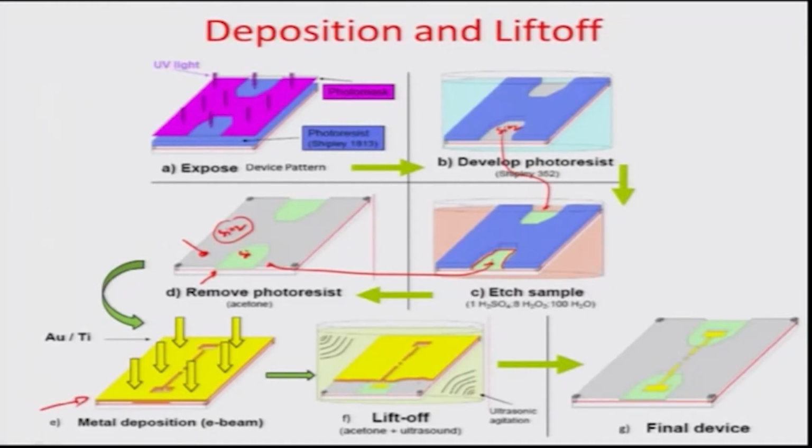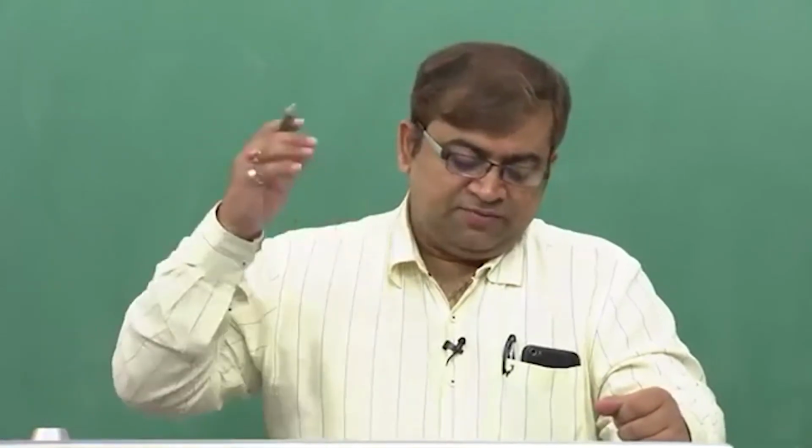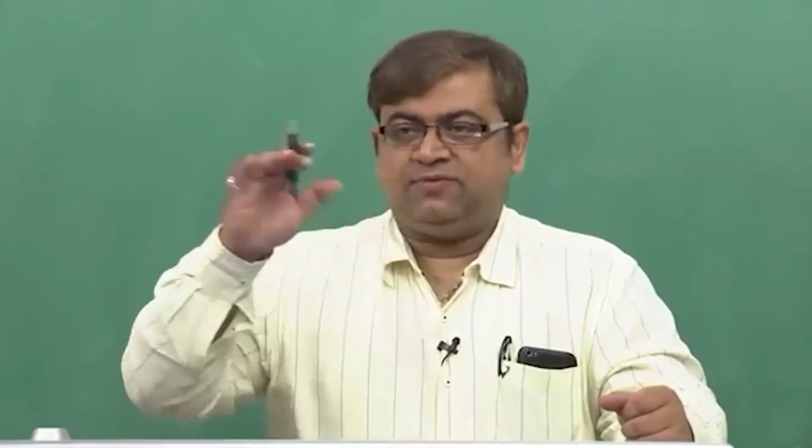I can use this for a different alternate protocol, where I can again make a sputtered film, again make a photolithographed film or a resist film on the top with another set of lithography where it removes these regions typically, and then deposit metal, which can be deposited by a variety of ways and means, which we will cover in a little bit later topic. One of them is called thermal evaporation, another is called sputtering. So there is a deposition of a metal vapor typically, whether it is in plasma form or in passive form, on the top of a wafer.